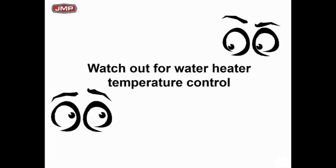So quickly we'll move on and we'll go back to what are our problems with domestic hot water. Where should we slow down and recognize that that little 2 GPM pump at 5 or 6 feet ahead is going to get me in trouble? Watch out for water heater temperature control. Nothing beats a little storage. So anywhere you don't have any kind of storage, instantaneous water heaters of any type, be aware you may have supply temperature control issues if you don't over-recirc them, if you don't change your recirc ideas or have a little bit of storage. Either one works.